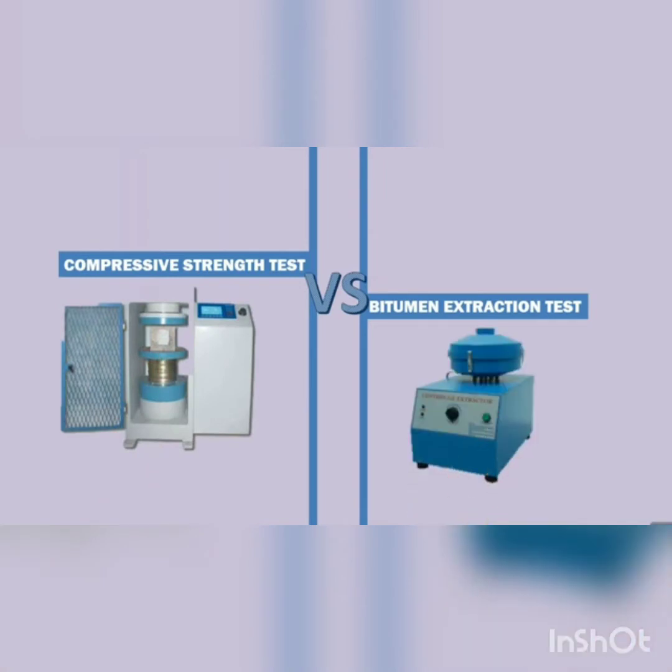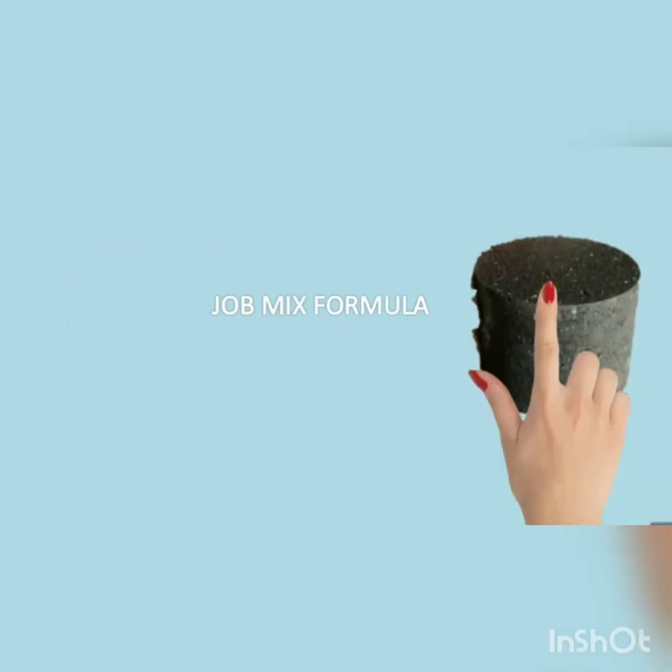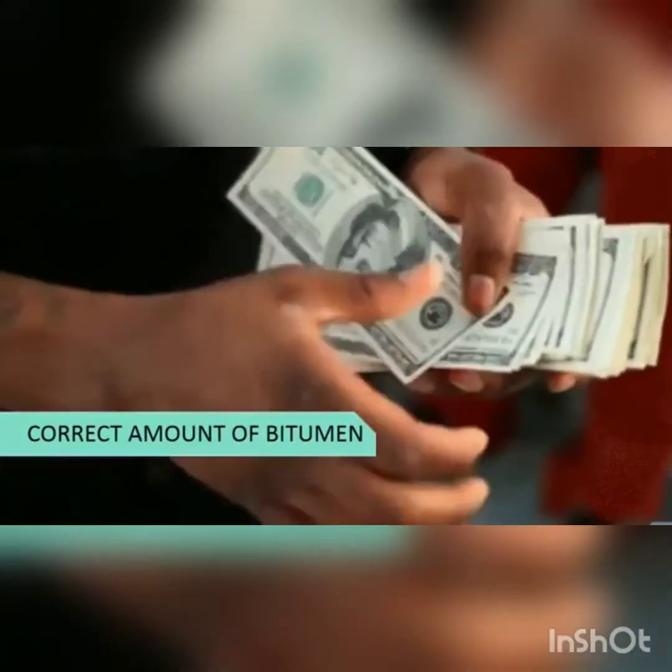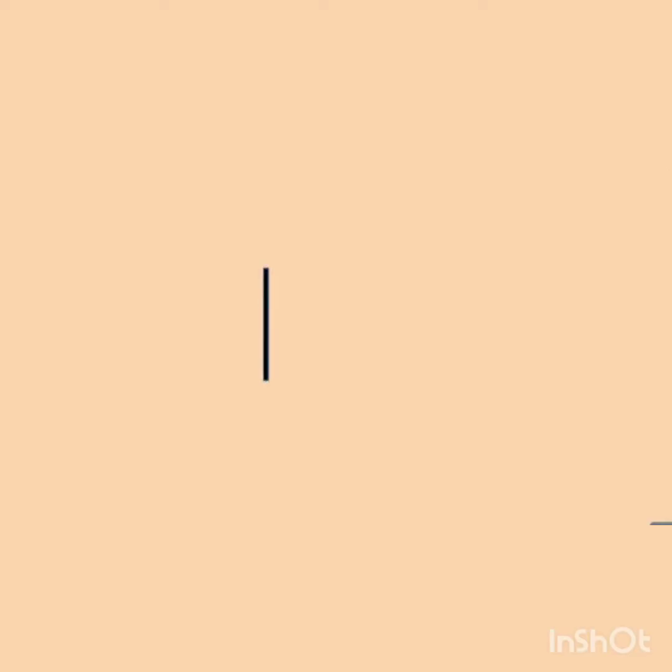The mix design of asphalt is carried out by a series of hit and trial in job mix formula for determination of the optimum binder content. So at site, before final payment to the contractor, it must be ensured that the amount of bitumen required by the mix design is actually used at site or not.